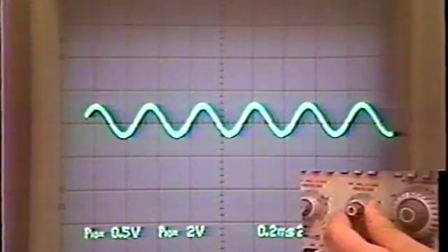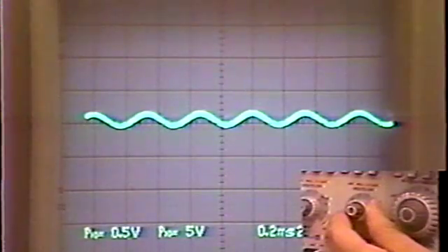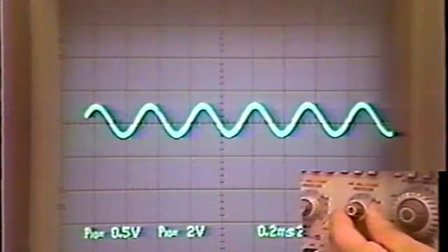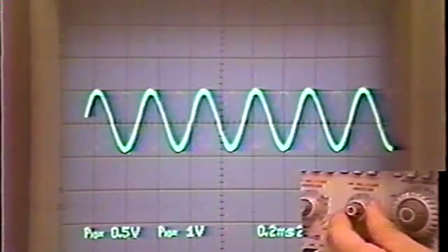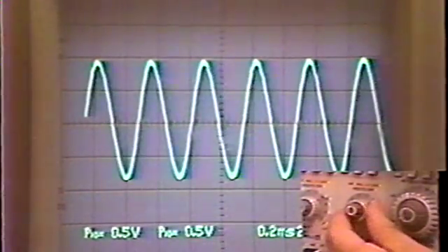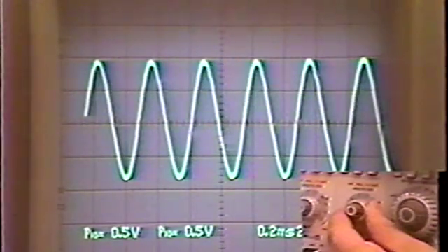Vertical adjustment of a waveform is performed using volts per division. A grid on the screen indicates the voltage value set using the dial. When the probe attenuation ratio is 1:1, the voltage is shown directly. But when the attenuation ratio is 1:10, the value is multiplied by 10.